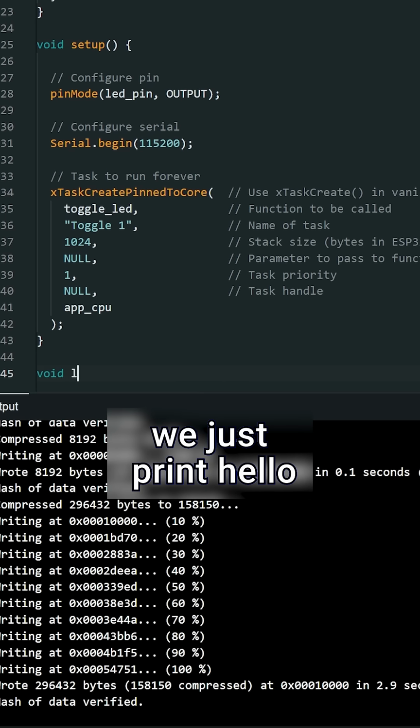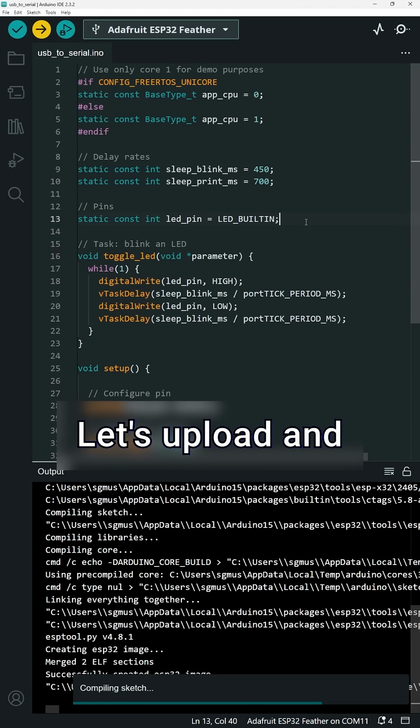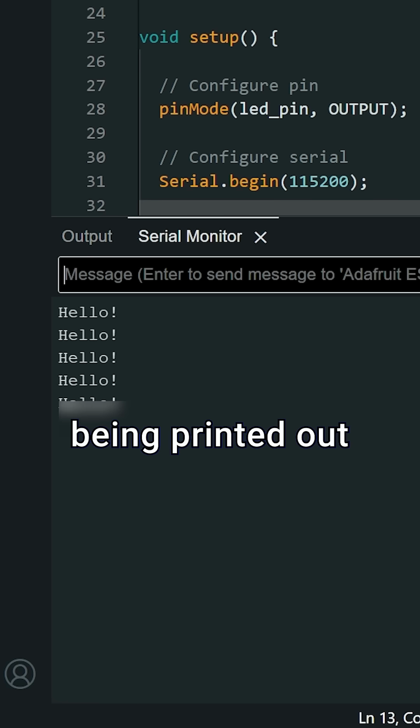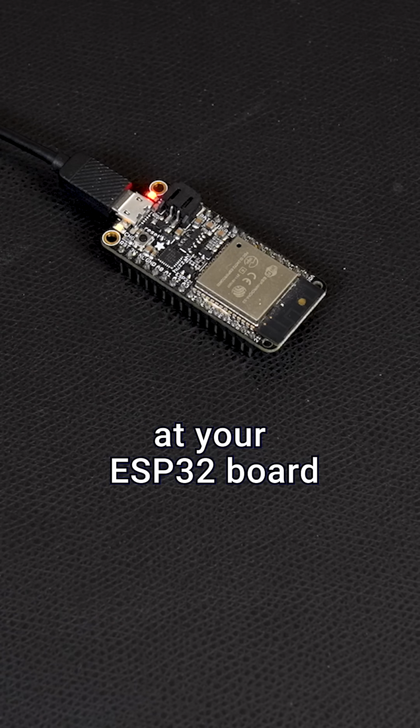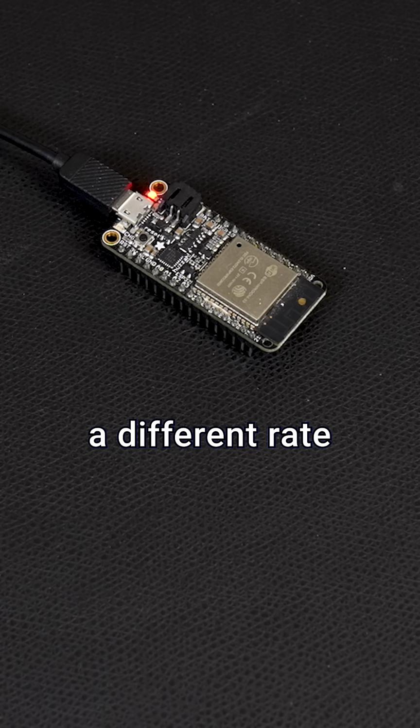In loop, we just print hello to the serial terminal every 700 milliseconds. Let's upload and run this. If you open a serial monitor, you should see hello being printed out. Take a look at your ESP32 board and the built-in LED should be blinking at a different rate.